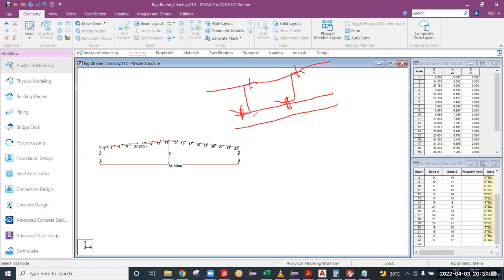The purlins run over the length, right? Like this. In the Z direction, they protrude out of the screen, right? So they will provide some flange bracings. These flange bracings will support the bottom flange at this portion. So that is why a complete purlin will support the rafter. If there is unsupported length, the rafter flange may buckle.